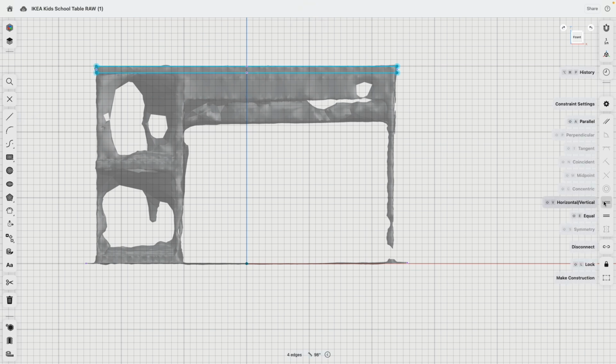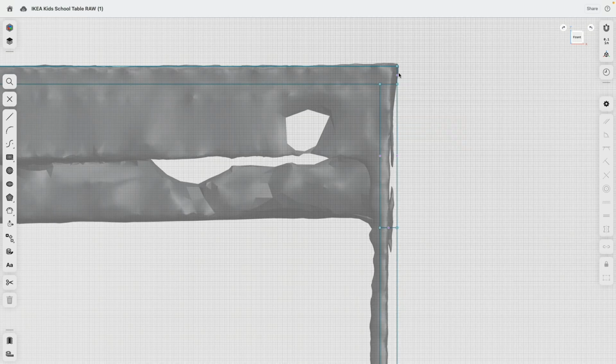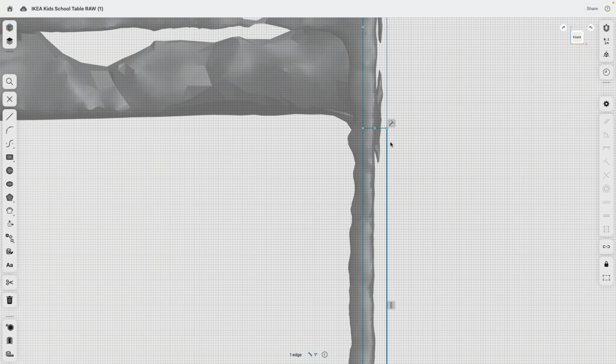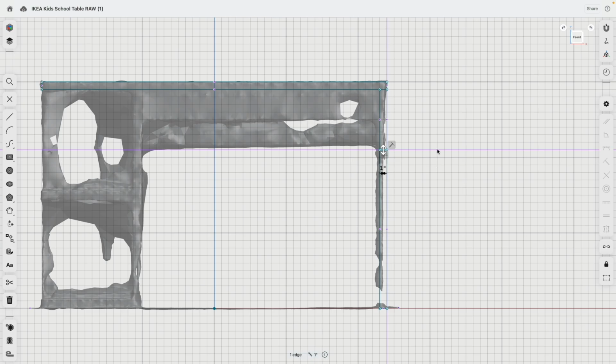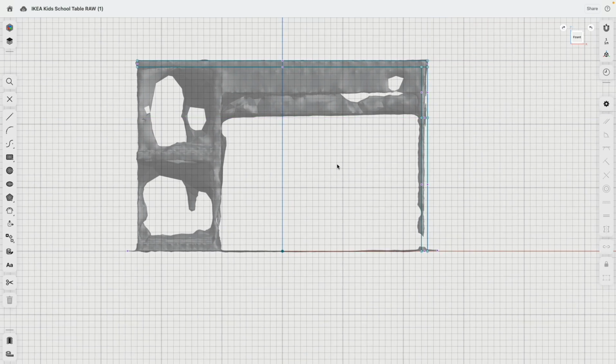Let's double select everything, and not double click to select it. Vertical, horizontal. So that's a tabletop. We have here, kind of like so, say 8 inches, a line going down, 1 inch up and back, and then from here another line over, down to the left and back up. Also here, make sure everything is horizontal, vertical. This is 1 inch, that is good. This is 1 inch, that's good. I don't add the dimension constraints to it because I think this should be pretty solid.